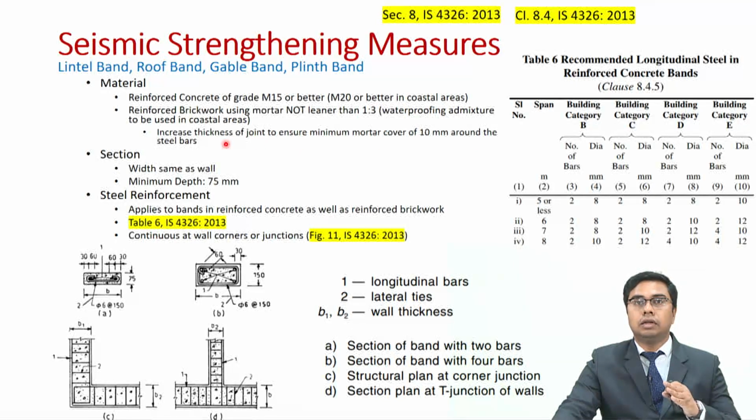Now you might recall from our previous lecture 9.1 probably, that we have told that the cover around the reinforcement shall be at least 15 mm of clear cover. So though the code gives you contradictory minimum cover requirement for steel bars, we suggest that you should follow minimum clear cover to be as 15 millimeters in that case.